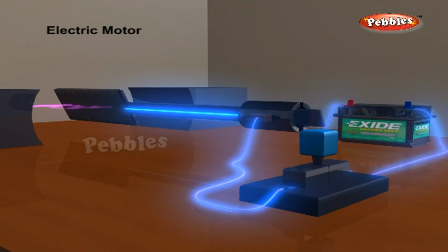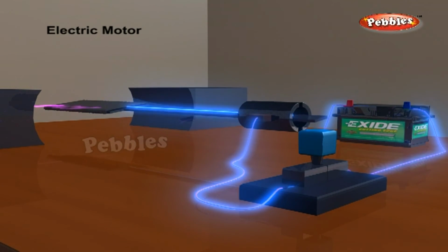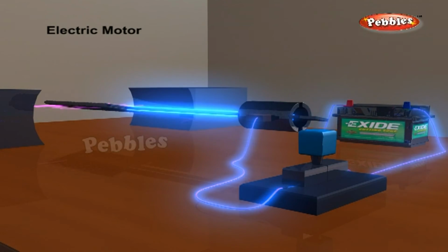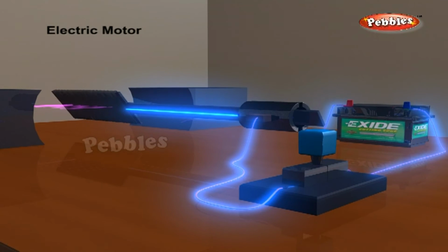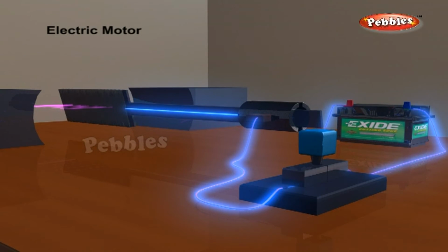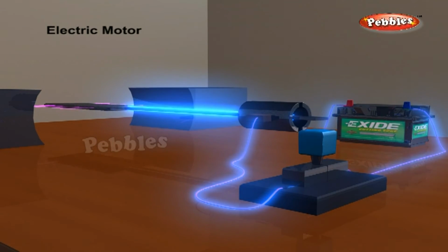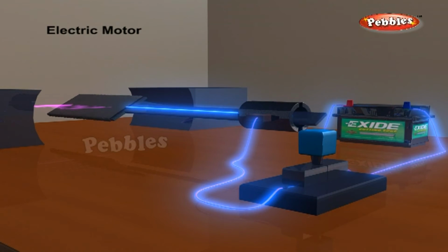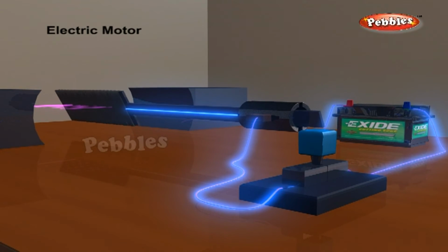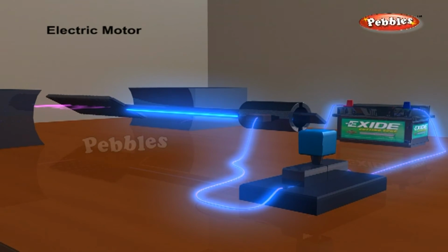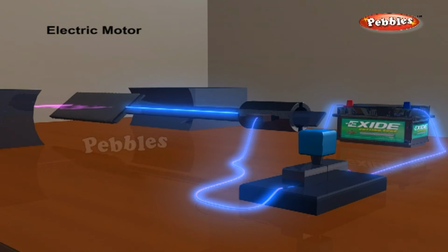On applying Fleming's left-hand rule for the direction of force on a current-carrying conductor in a magnetic field, we find that the force acting on arm AB pushes it downwards, while the force acting on arm CD pushes it upwards. Thus, the coil and the axle O, mounted free to turn about an axis, rotate anti-clockwise. At half rotation, Q makes contact with the brush X and P with brush Y.